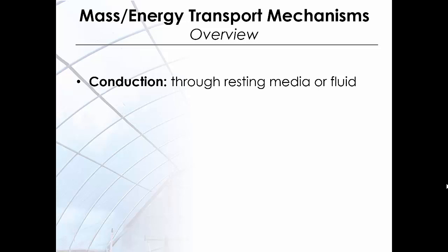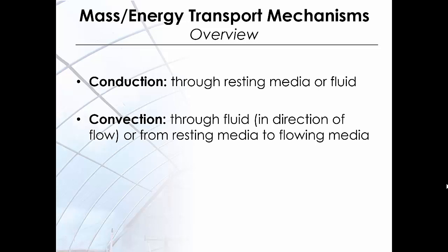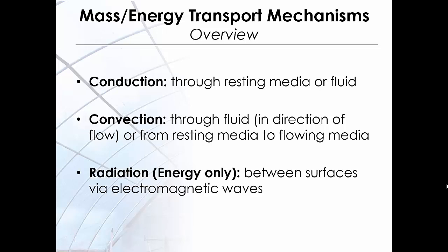Conduction is the transport through a resting medium, solid, or through a fluid not in the direction of the flow. Convection is the transport through a fluid in the direction of the flow, or transport from a resting medium to a moving medium. Radiation, for energy only, is the transport between surfaces of opaque bodies by electromagnetic waves through a transparent medium.